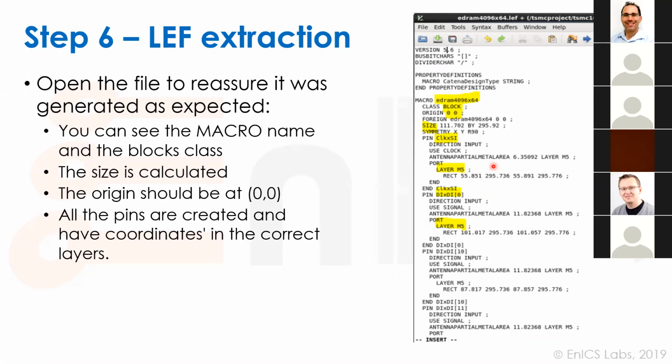Because in the end, we'll run our DRC check and we'll see this violation, but it's too late because we've already closed up our macro. We don't want to make any of these ECOs, these changes at the last second when we already have our GDS out. We want to do it while we're routing. So yeah, to take it into account, to solve the problems when it's easy to solve and not when it's hard to solve.